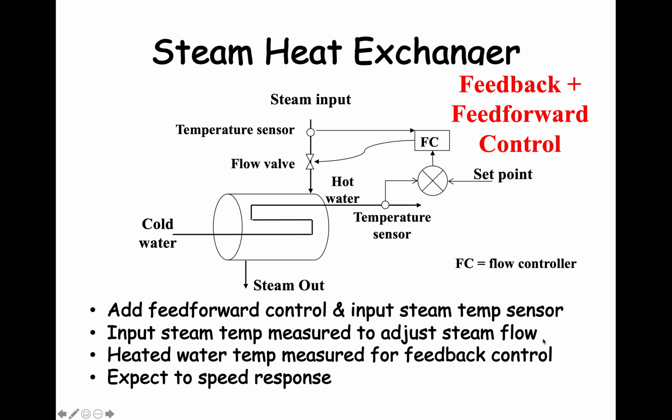This slide shows our steam heat exchanger with a temperature sensor in the steam input line. We now have feedback plus feed-forward control. We will use this steam temperature as an input to adjust the steam flow valve.